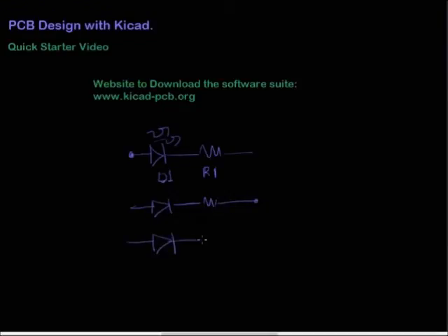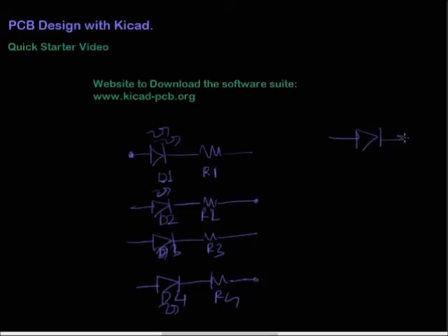So let's say this is the schematic: R1, R2, R3, and we will also have R4, and these are the LEDs: D2, D3, and D4. Now KiCad takes LED. Now there are 2 things to it. Now this is a component. Obviously it's a LED, and this LED has 2 parameters. So one is the value and the other is the reference. Now what we denote here is the reference. So now reference is like D1, D2, etc.